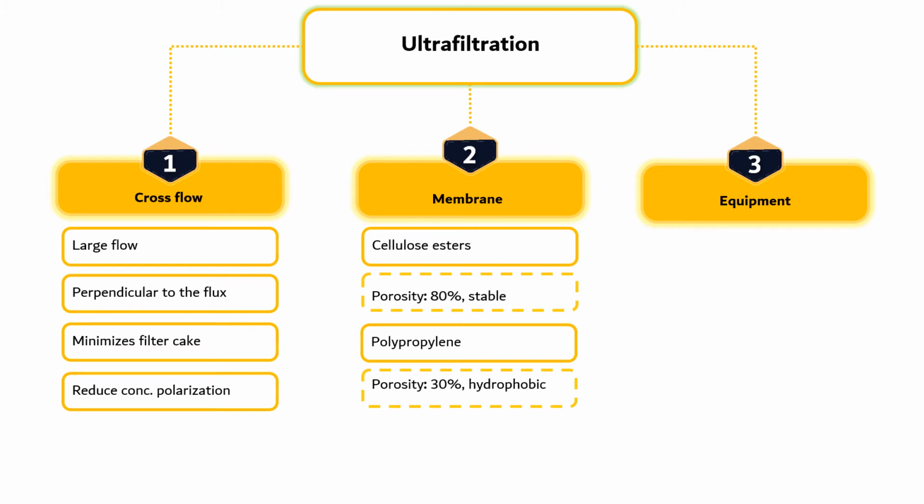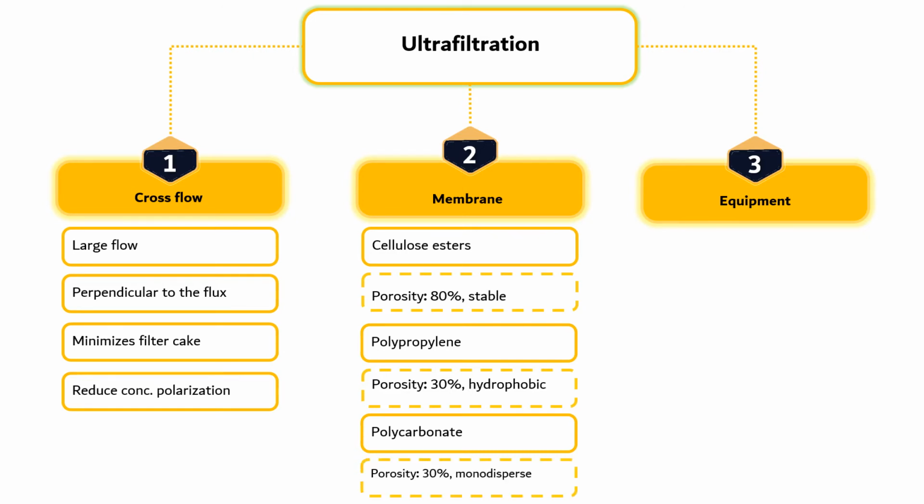The third membrane type is made by exposing non-porous films of mica or polycarbonate to radiation. The radiation tracks in the film are then etched away with hydrofluoric acid. This membrane has the lowest porosity, around 3%, but by far the most monodispersed pores.